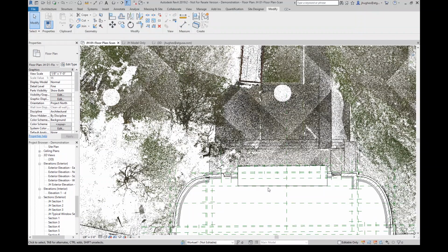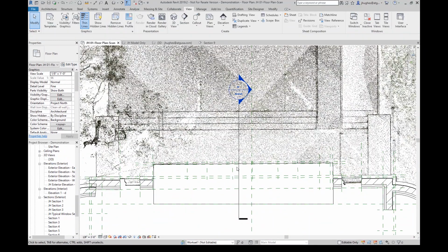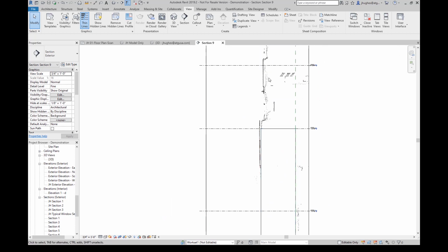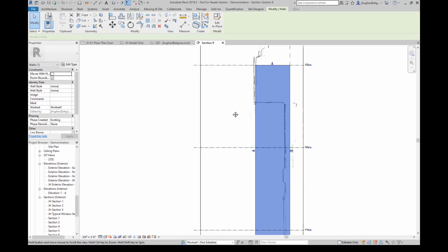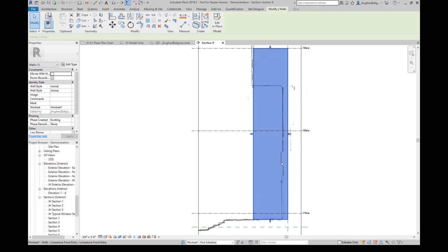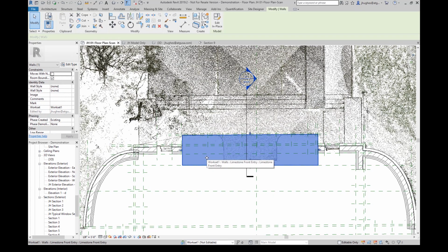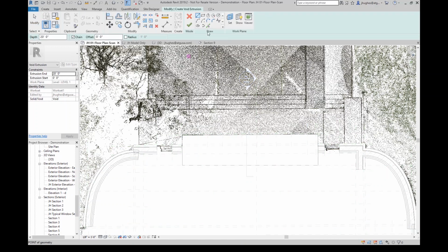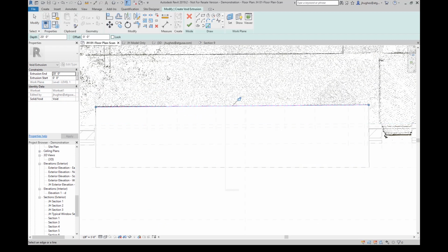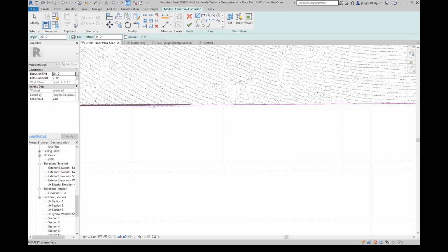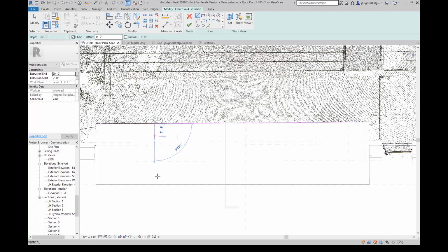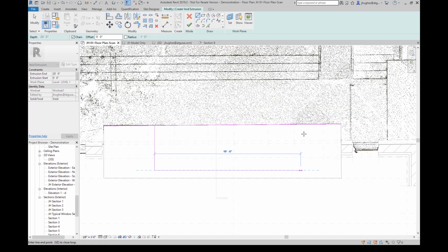It's actually going to be hard to be able to see the cutaway piece while that's there. But if we look at a section cut through here, we can see the floor, we can see the top profile. And if we click on it, we can actually see that flat top returning to where the door system is. So I'll select it, edit in place. We'll create this time a void extrusion. And I'm going to carve away a bit extra here. So I'm going to select this exact front line and then very carefully try to go down. And I'm going to remove extra just so I can see the part that we're getting rid of.